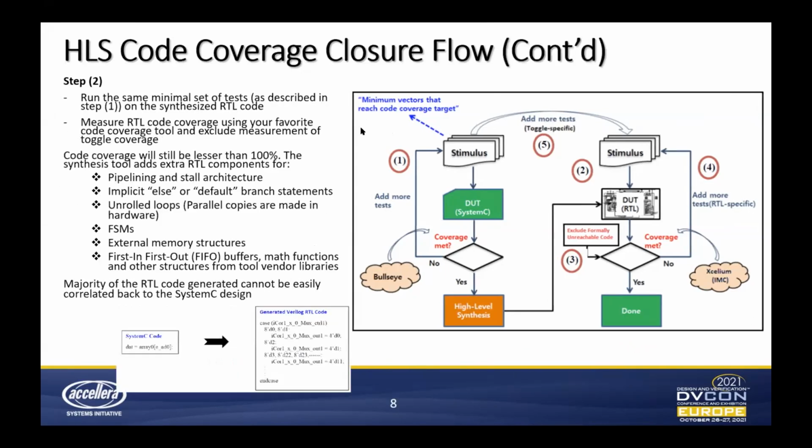This slide explains step 2 of the code coverage flow. Once synthesis is performed, run the same minimal set of tests as described in step 1 on the synthesized RTL code. Measure RTL code coverage using your favorite code coverage tool. Exclude measurement of toggle coverage here, and the code coverage achieved will still be less than 100%.